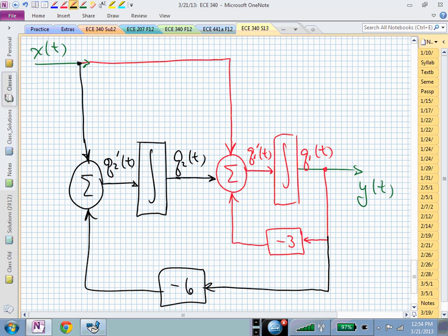If you had a non-zero D matrix, you could have a path, and that's where this direct feed-through comes from. That terminology is the input x is now directly coming in and being seen at the output y. And it might also have some filtered inputs and outputs with it.